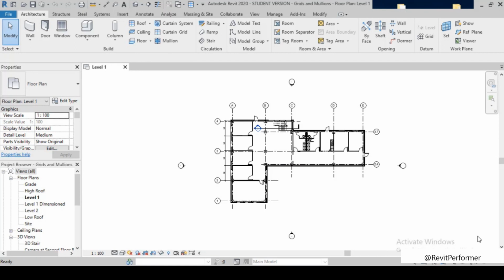In this lecture, we're talking about adding curtain grids, mullions, and panels. In this movie, we're going to continue our exploration of curtain design, and I am going to build a custom design. We saw in our previous movie that if you do curtain wall type, you can configure a set spacing in both the horizontal and vertical dimensions. But you can actually do any kind of variations.